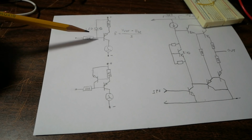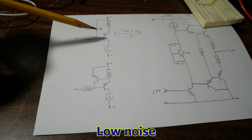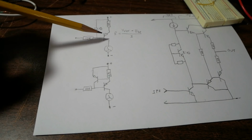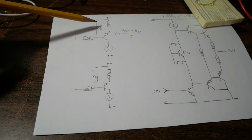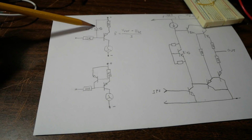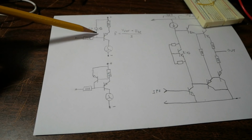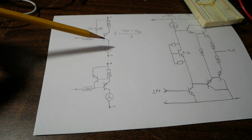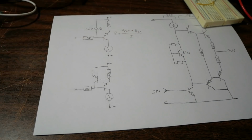Well, the reason being is a green LED is supposed to perform really well. It's supposed to have good thermal matching with this transistor to keep the current pretty well in check. So it is quite common to see a green LED used in some amplifier designs. Plus, it has a fairly low voltage drop of around 1.8 volts at the current that it's going to be conducting, and we need that low dropout voltage for this circuit to keep it operating properly in the VAS stage.